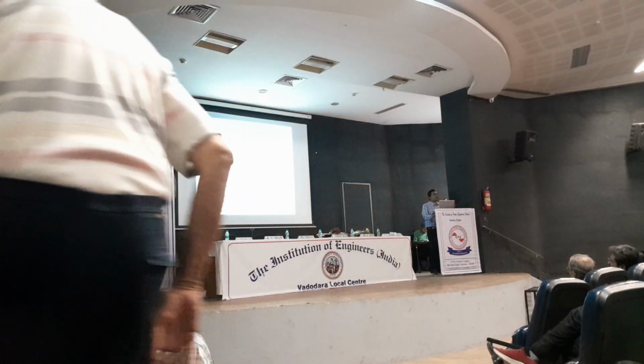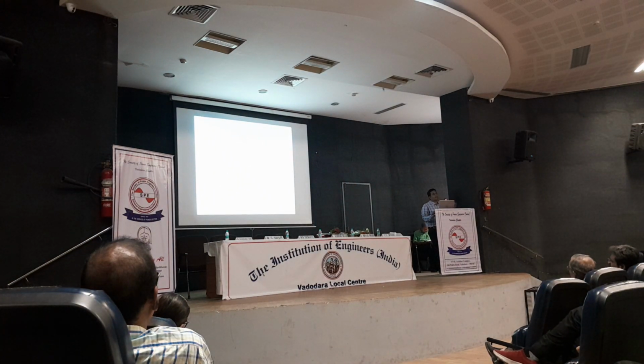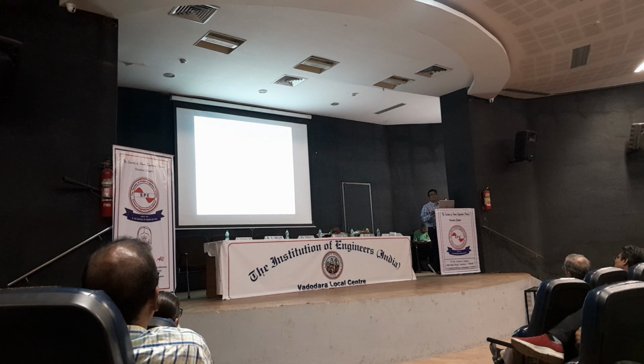As you already know, there are two kinds of fault in a power system. One is symmetrical fault, one is unsymmetrical fault. In symmetrical fault, all three lines participate during the fault, and in unsymmetrical faults, you know that single line to ground, line to line, or double line to ground faults will be there. So one more case we discussed. Let's say some network is given in this form, where a generator is there, a transformer is there, and a 3-bus system is there along with their impedances.